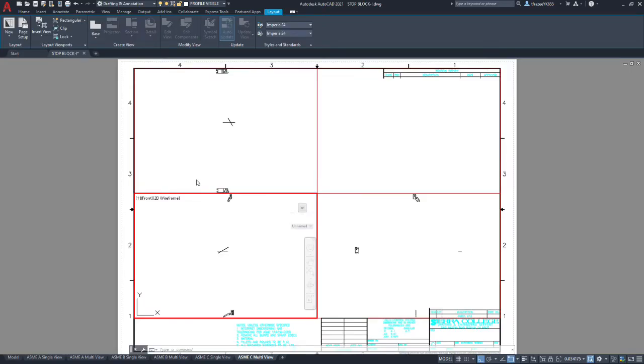I'm going to focus on these two first viewports and get our two initial views placed first. Then we're going to go through a process of trimming those viewports, and we may need to insert an additional viewport. So here we go. We zoom extents in these two views. Now we need to roughly center the view. So this viewport in the bottom is going to be our front. So we want this view down here. And make sure it's set on front.